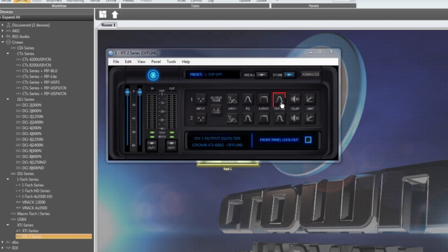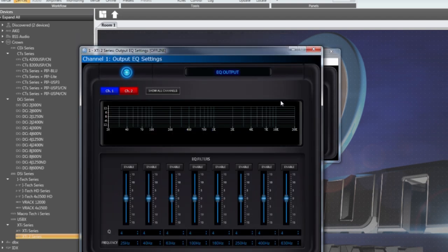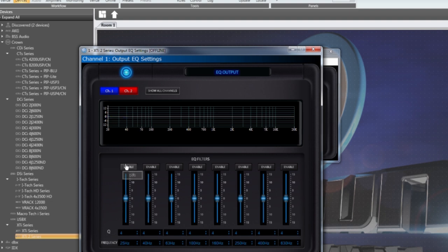The next option is the second of the 2 EQ options. The Out EQ is post high-pass and low-pass filters, which give the ability to EQ within the frequency ranges set up in the Crossover section. There are 8 available parametric EQ points. There's a Q option to span a range of frequencies, or notch out frequencies, and faders to boost or cut each EQ point by plus or minus 15 dB. This is only available in the software.